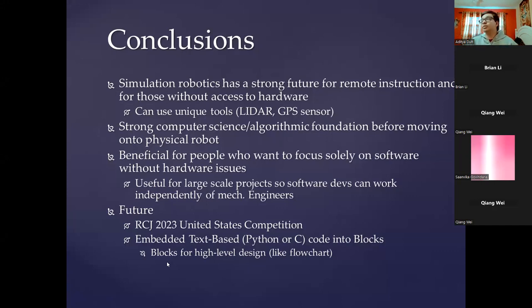So for example, if somebody is doing a rescue line competition, they can deal with just the software, getting the algorithm of their code perfect, before moving on to the physical robot, because in the physical world, it's not deterministic, like I was talking about before, right? There's a lot of issues, there's some noise in the world, sensors don't always work perfectly. And for somebody who wants to focus on the software, it's really frustrating to have to deal with hardware issues and not knowing if your code is an issue or if the hardware is giving you an issue. So simulation is really good for that.